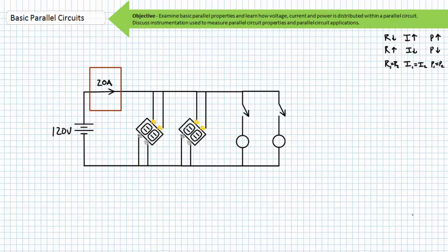Consider electrical distribution within a house. In the United States, residences are typically supplied by 240 volt, single phase, 60 Hz AC. Some branch circuits like stoves, dryers, washers, or other heavy-duty equipment require 240 volt supply voltage. The 240 volt input, however, can be split into two legs of 120 volt AC and then subdivided into branch circuits, each at 120 volts AC. You may not understand all the terminology I threw in there, but let's use this simplification.